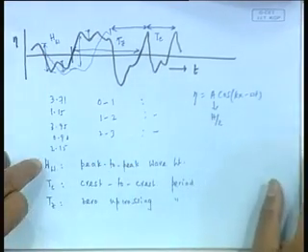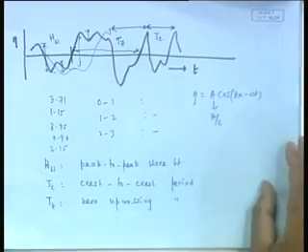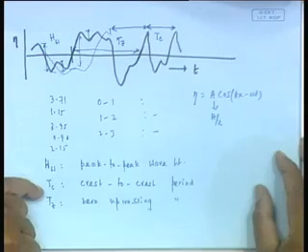But having said that, let us say I have a histogram for Hw. Well, I know that the chance of wave height exceeding 10 meters is so much. I also have a histogram of Tc. So I can say that the chance of a wave occurring with more than 15-second period is so and so. But are they not connected to each other? This information does not relate the two. For example, it cannot tell me which height and which period are related.